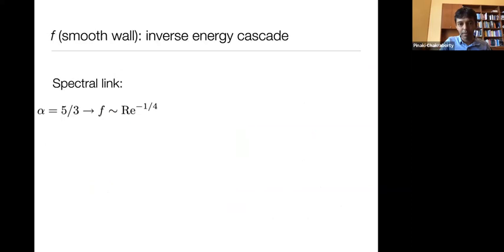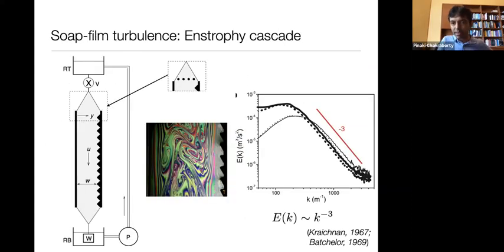Okay, so for example, let's start with this. What we did, we had to make sure that we have flows with uniform spectrum. So we started effectively right outside the viscous layer and all the way to the center line. The dark lines that you're seeing over here are the spectra measured about 1 millimeter away from the wall. And the light lines are the spectra measured at the center line. So we wanted to make sure that all across the width of the pipe, or the channel in this case, you have the same spectral exponent, which in this case is -3.